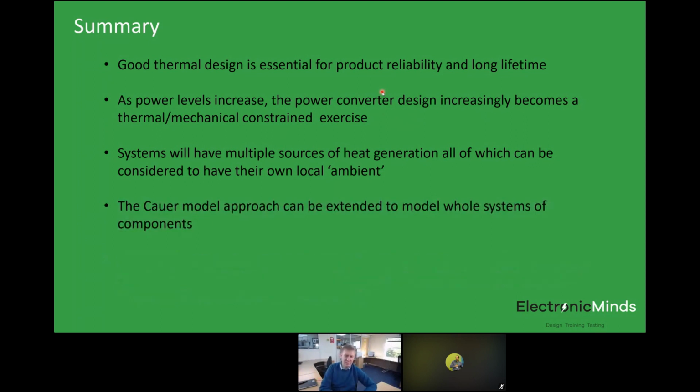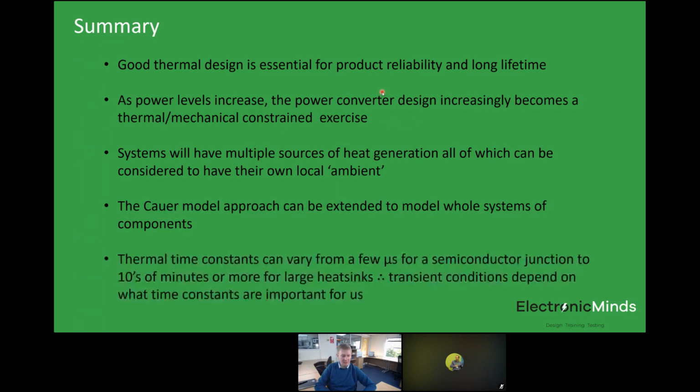The Cauer model traditionally is used in power semiconductor modeling, but I think it's a very useful technique, because it really relates to the physical elements of heat transfer, which can then be extended to the whole system of components in your power converter. And the key thing then is to understand the various thermal impedances and thermal capacitances involved in that system.